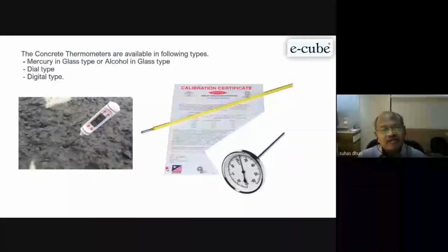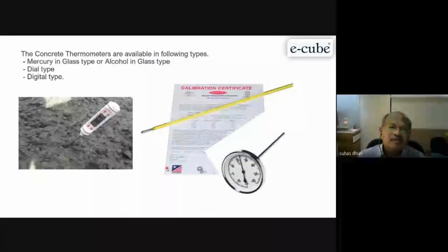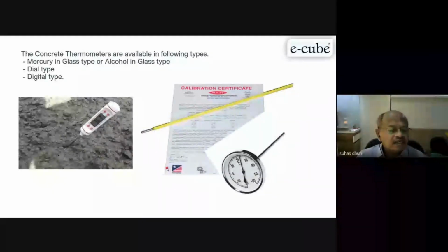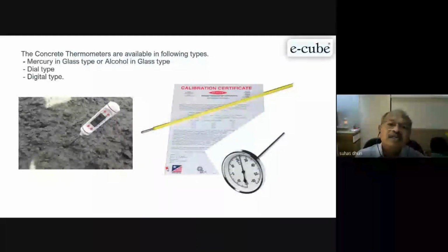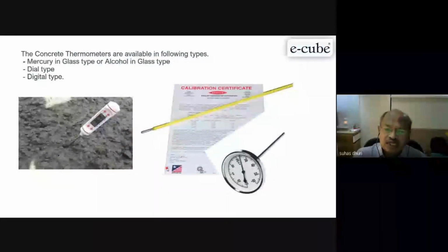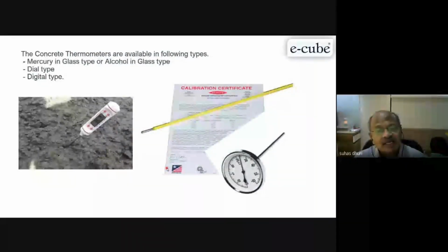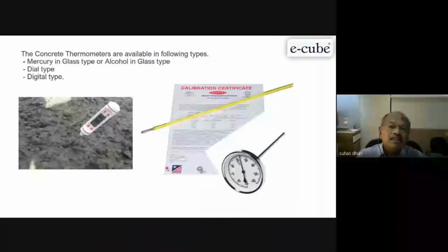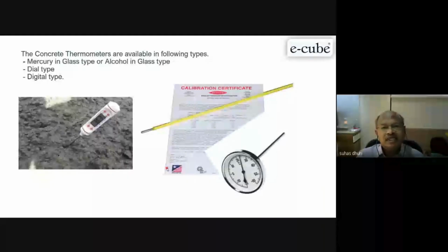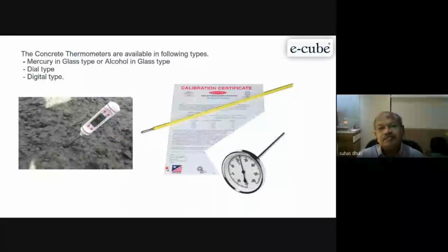Very rarely, suppose M20, 25 or 30 is there, for some small houses you can use slump concrete. Otherwise, most of the concrete is flowable concrete. Now, whatever question you ask, IS 456 has given the type of structure and what the slump requirement is. They have already given it. You can just refer to that table. But that may not be applicable right now in the current scenario, which is happening with concrete using crushed stone sand.